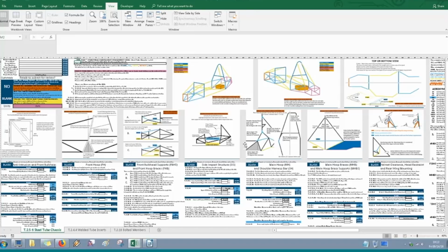A big change for this year is the SES has been split into different files. Internal combustion teams with a steel tube frame need to fill out the steel tube SES, plus the IAD, which is due at a later time. EV cars with a steel tube frame need to fill out the steel tube SES, plus an additional HV enclosure SES. That covers the accumulator, attachment, HV protection, and that's due at the same time, plus the IAD, which is due at a later date.